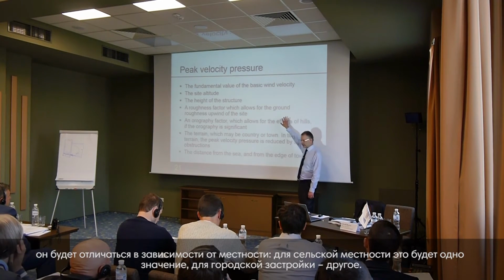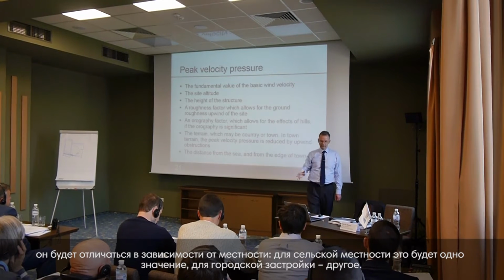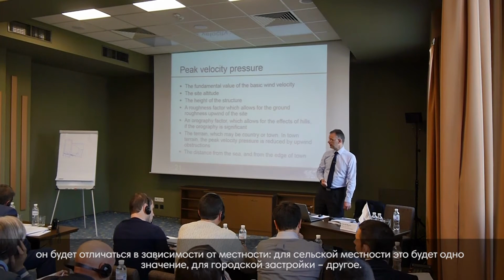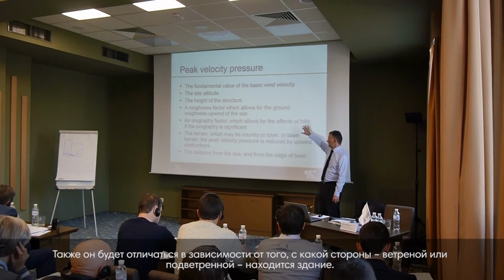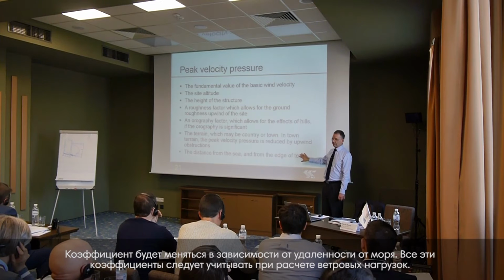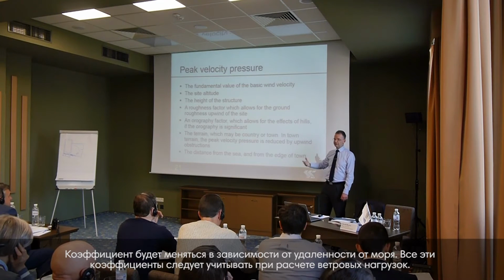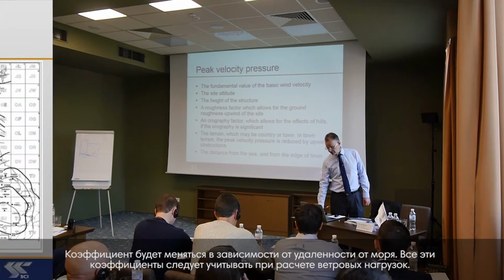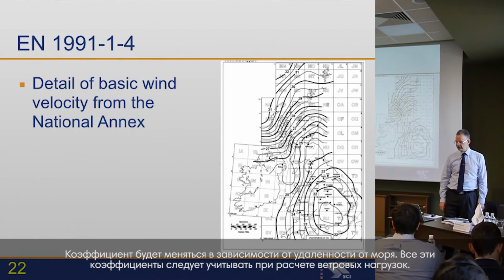So if you are in a city or in a built-up area, it will be different to if you are in the country. If you are on a slope of a hill, it will be different. The upwind slope or the downwind slope. If you are far from the sea, it will be different. So all these factors go into the calculation of the wind loads.